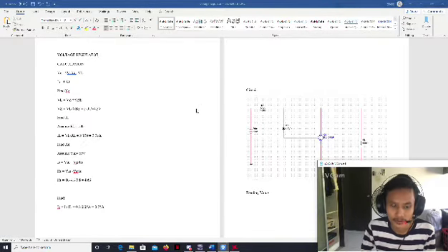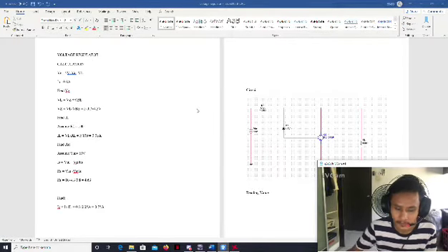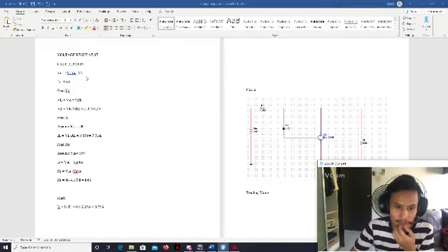Today I would like to present about the assignment. My part is the voltage regulator. First, I will show the calculation for the circuit. The VO and the IS are provided by the equation, which is 5 volt and 0.8 ampere. The first step is we must find the VZ. The general formula is VL equals VZ plus VBE. So VZ will be 4.3 volt.